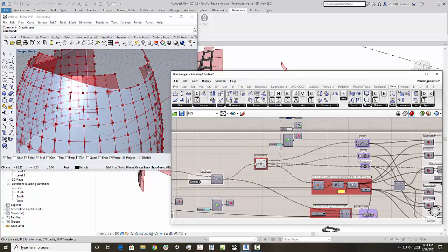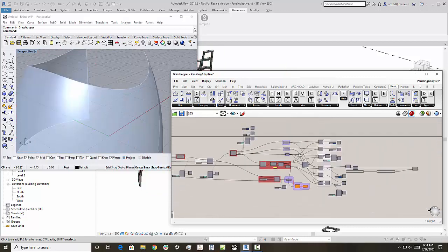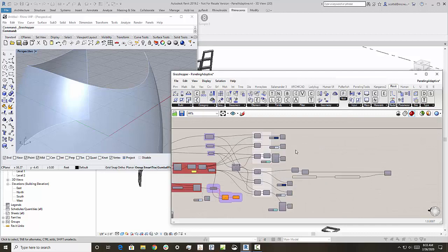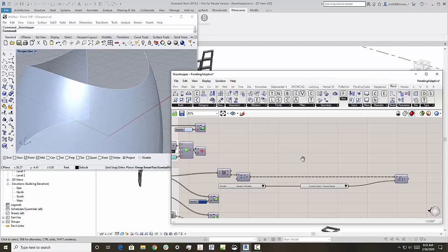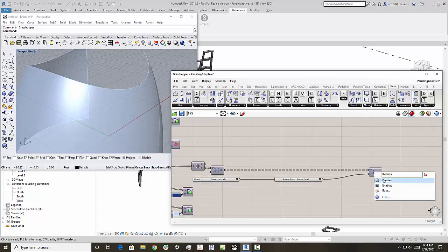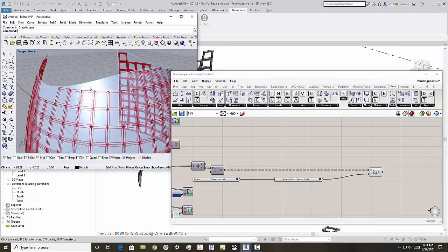And so let me just turn that off there. And we'll just come down here. So we go through the process of filtering what's inside and outside. And if we come down here, I can open these up. And you can see here, generally the easiest thing to do is to use paneling tools to place four points at each one here, and then place an adaptive component using that original add adaptive component that we talked about at the start of this.